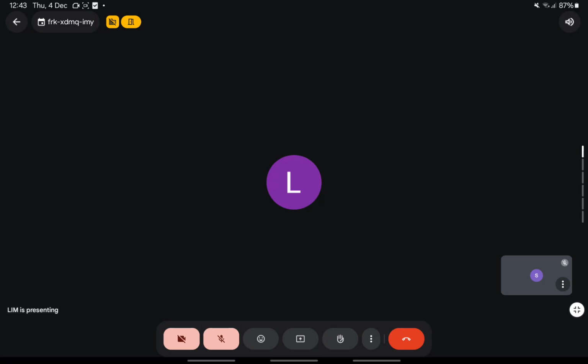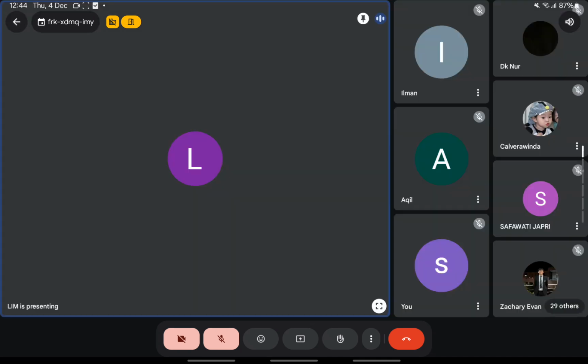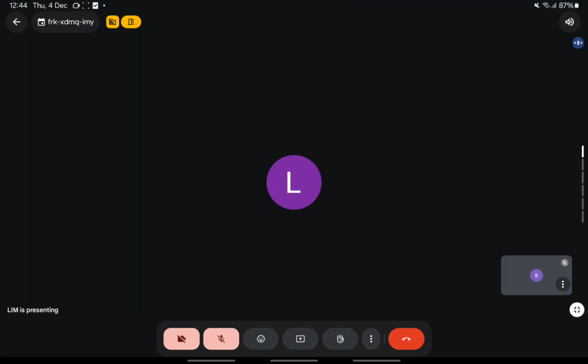The BS 8110 table also depends on whether it's a braced or unbraced column, and it also depends on the top and bottom condition. So very similar to the Eurocode one. It looks at the condition at the top and the condition at the bottom.